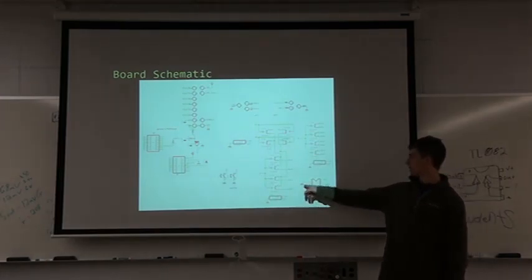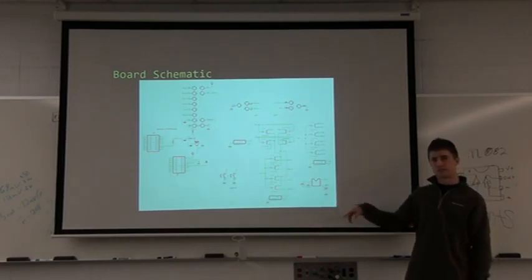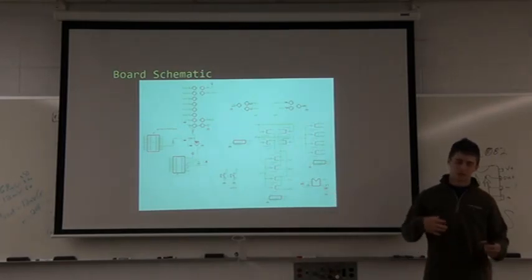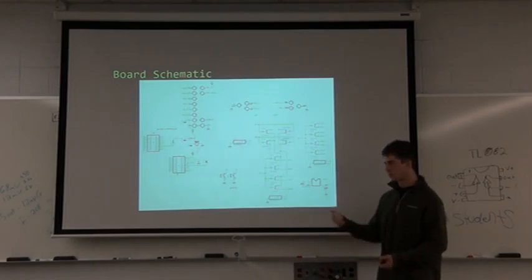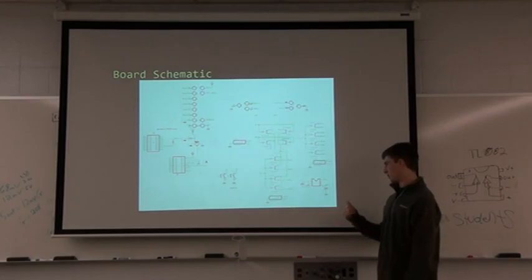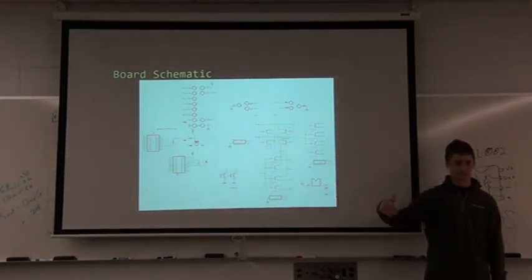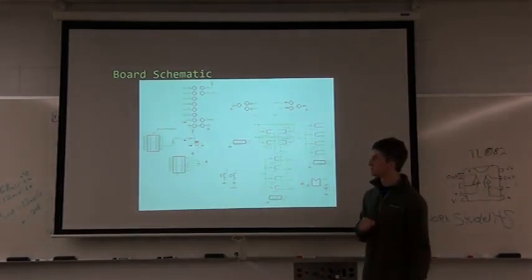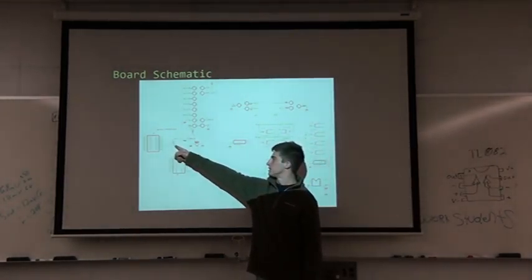The capacitors were given in the schematic of the 7662, and they gave a bunch of different wiring options for different uses of the device, and so I just chose the most common use, which was to create a negative supply, which they said use two 10 microfarad capacitors.